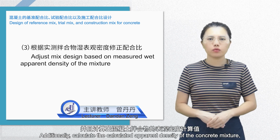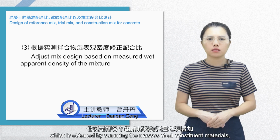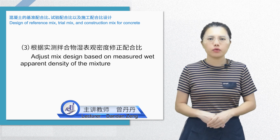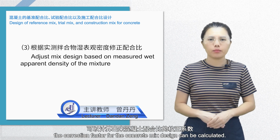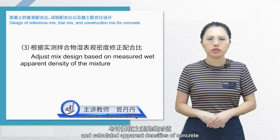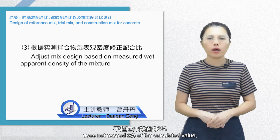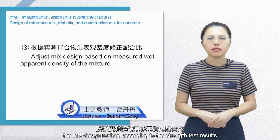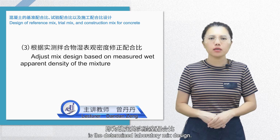Additionally, calculate the calculated apparent density of the concrete mixture, which is obtained by summing the masses of all constituent materials. Furthermore, based on the measured apparent density of concrete, the correction factor for the concrete mix design can be calculated. When the absolute difference between the measured and calculated apparent densities of concrete does not exceed 2% of the calculated value, that is, when the correction factor is less than 1.02, the mix design revised according to the strength test results is the determined laboratory mix design.